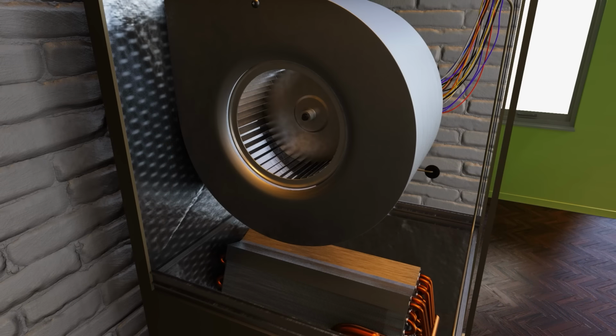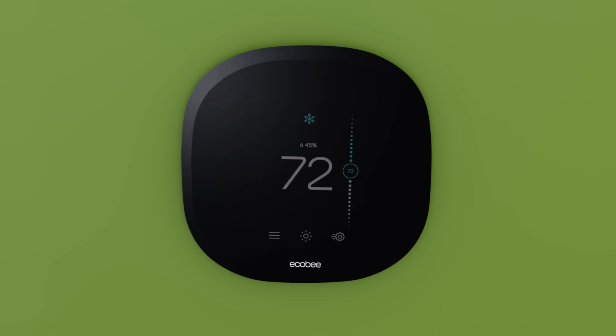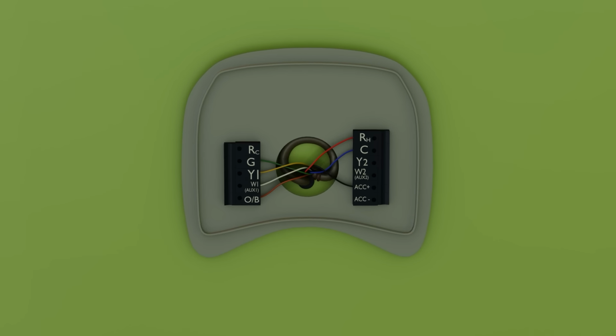The transformer takes the high voltage power, on a fan coil that's generally going to be 240 volts. On a gas furnace, that would generally be 120 volts, and it's going to convert it down to a safe 24 volts that we can then use to energize the low voltage circuitry on the system. That's going to go to your thermostat.